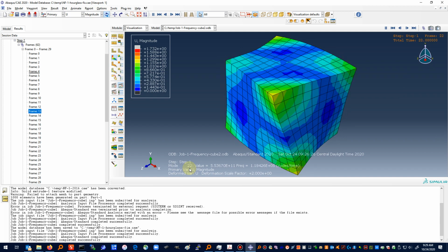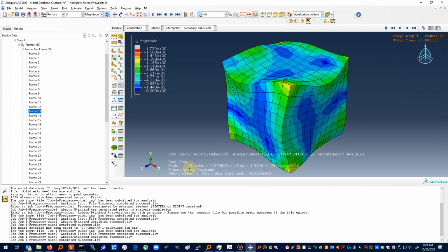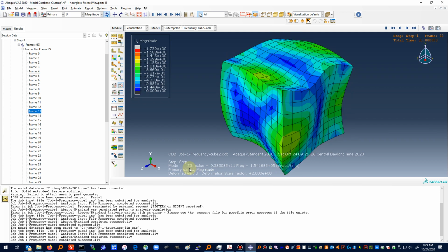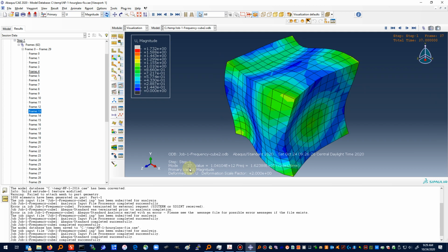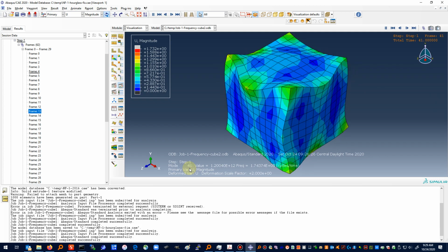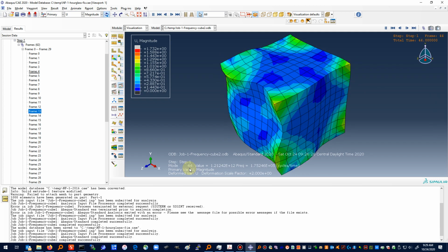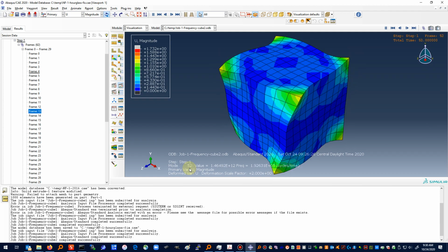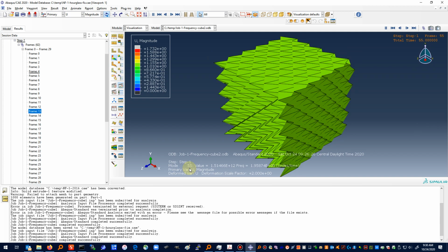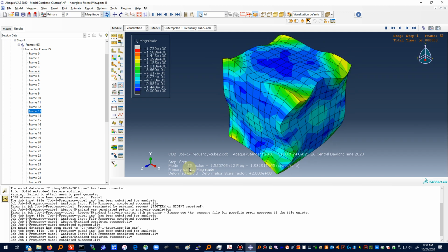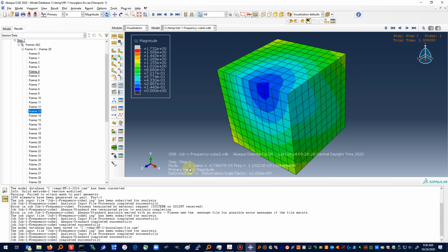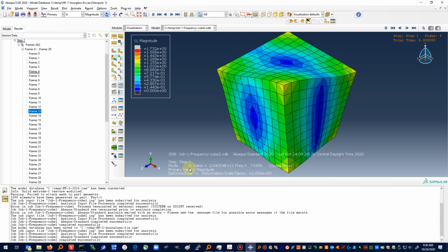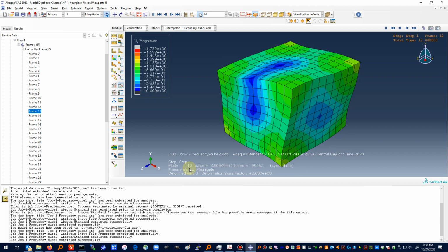You can put accelerometers on it, and you can hit it with an impact hammer, and you can determine the natural frequencies in something that approximates a free condition. Now, why do we worry about free at all when most objects are restrained in some situation? Well, some planes are not restrained. Okay, some planes are, and it's kind of a standard thing to do to calculate the free natural frequencies to get an idea of where you're at.